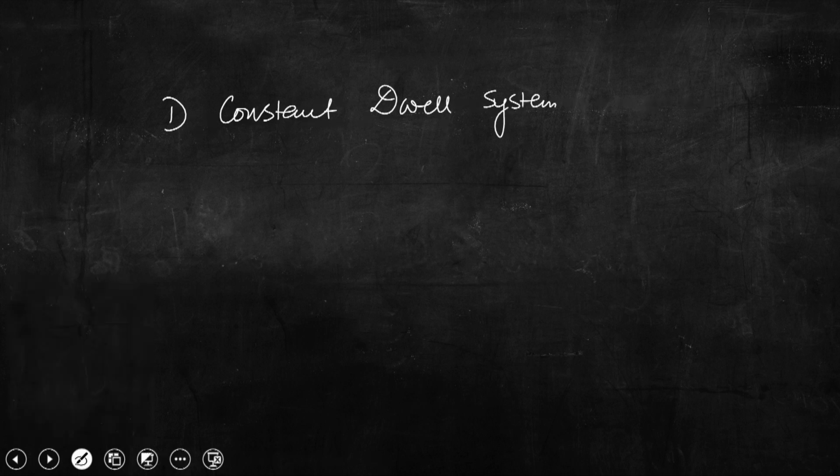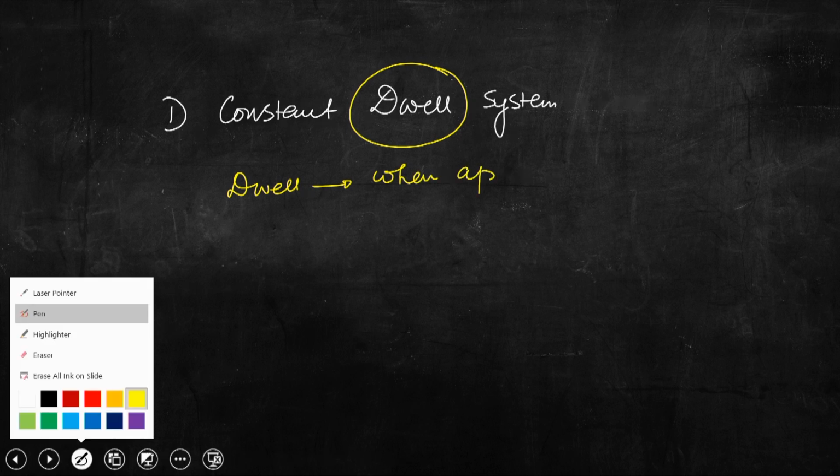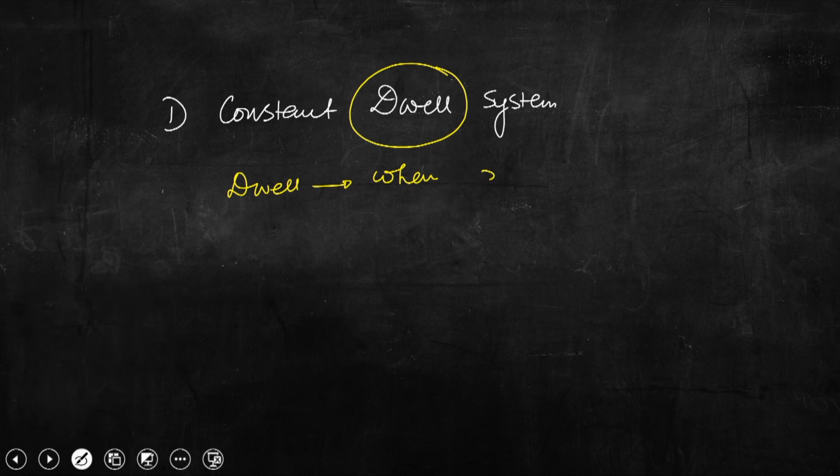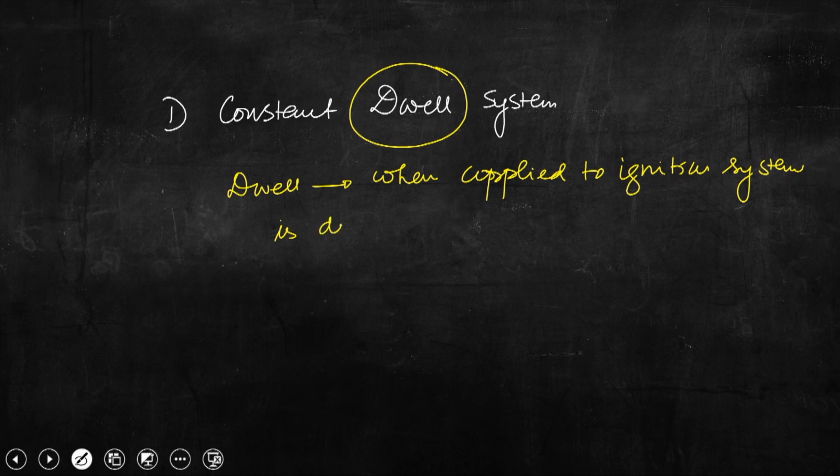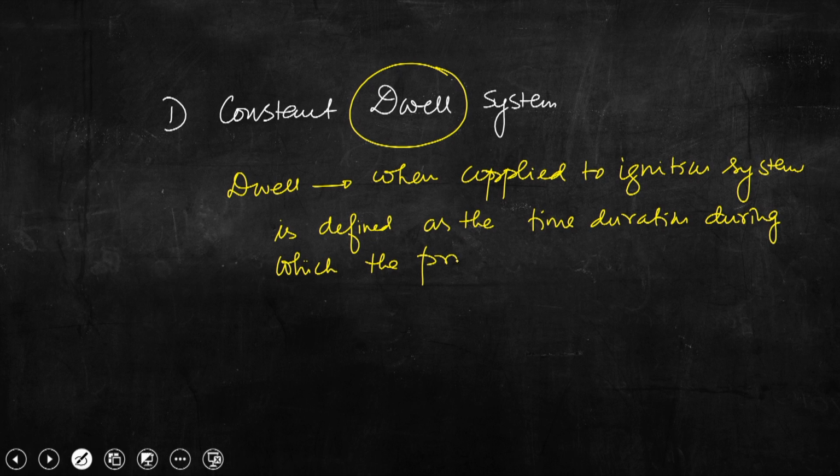The term dwell, when it is applied to the ignition system, is defined as the time duration during which the primary coil is charging.